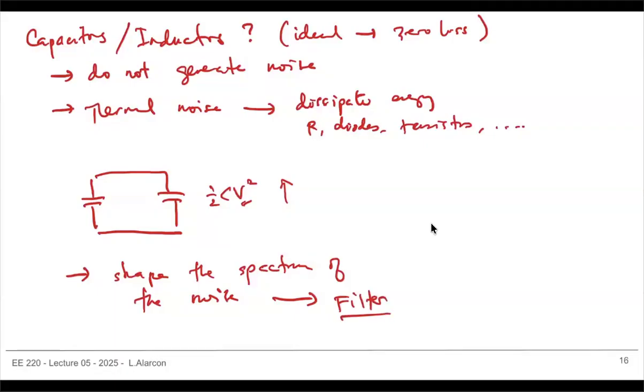One of the reasons why, we'll see, when we design amplifiers or low noise amplifiers, LNAs, in communication circuits, we actually want to start to limit your bandwidth, right? That means I don't want a lot of excess bandwidth. If I only need 2.4 gigahertz maximum, I want 2.4 gigahertz maximum. I don't want to say, oh, I'll put in some margin. Maybe I'll put in some like 3 gigahertz or whatever.